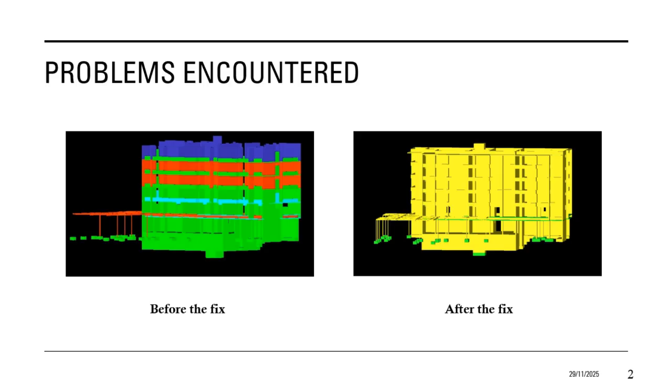This distorts the workflow, as the correct display of yellow for formwork removal is overridden by the color retention setting of the already completed phase. The solution involves ensuring that the end appearance in the task configuration is set to none, or the appearance of the base model.